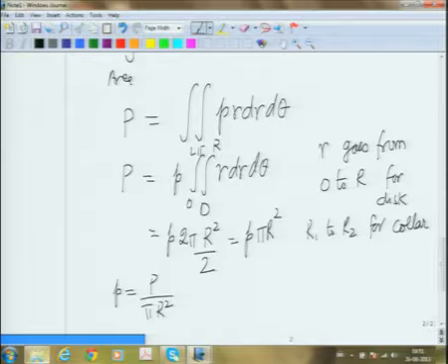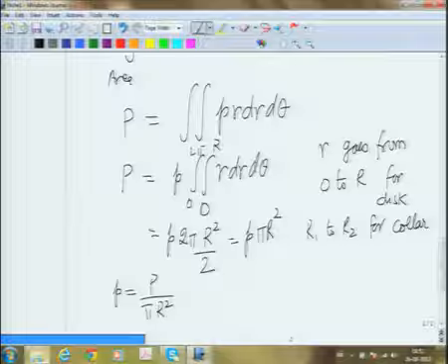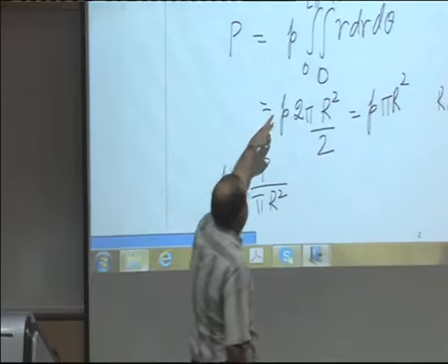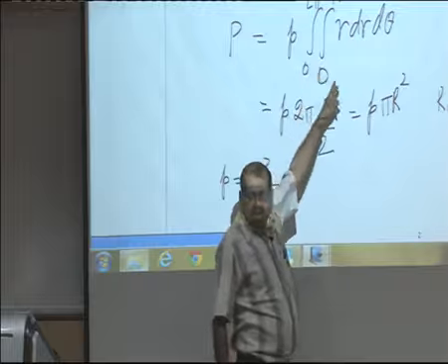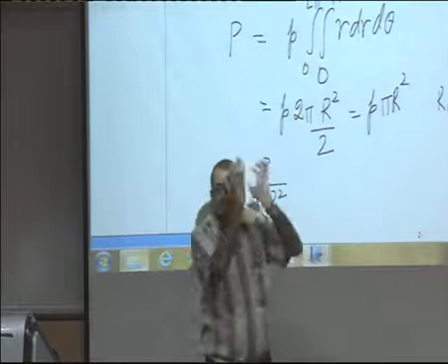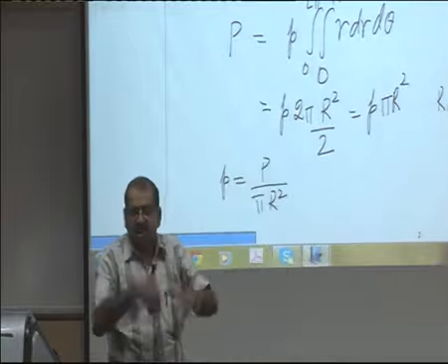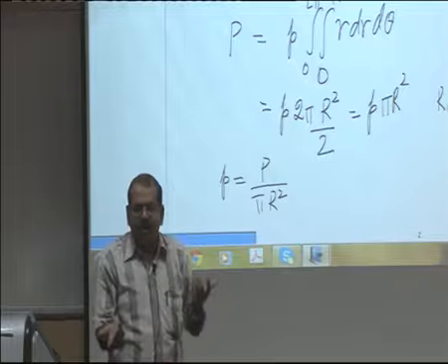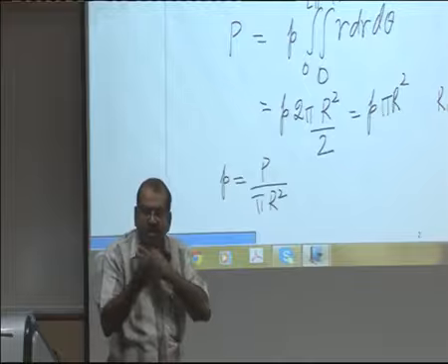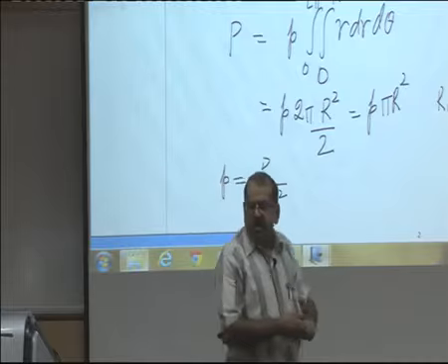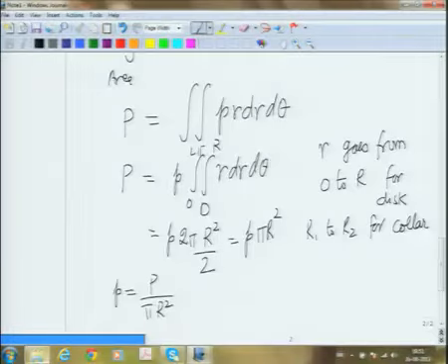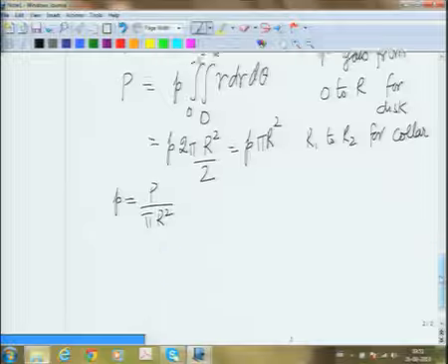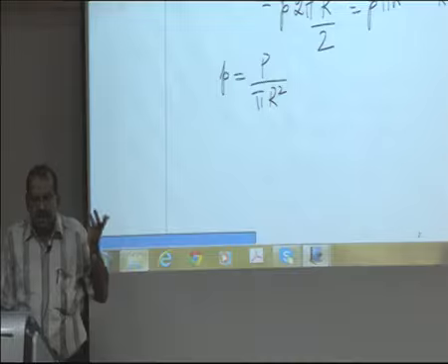Now, let us find out the frictional couple. So, here we have worked out the pressure, and the reason I have done this is it may be P had some form of R. If P was a function of R, then it would have come inside this integral. You would have got P of R, r dr, and then given that form of R, you would have integrated accordingly. So, it could have changed also. So, that is why I did it in this way, and maybe I will take an example which will further clarify this. So, this is small p.